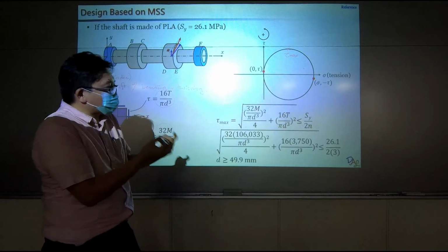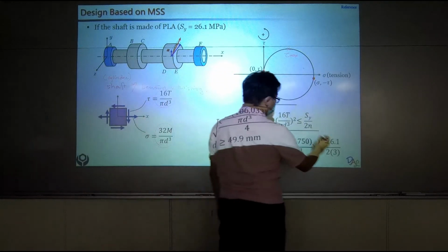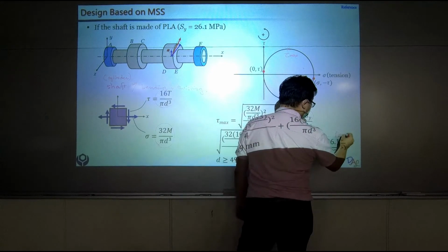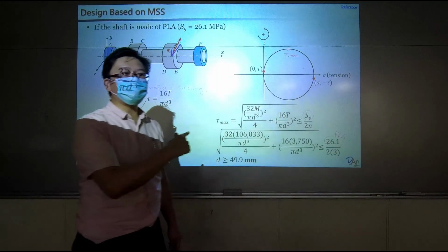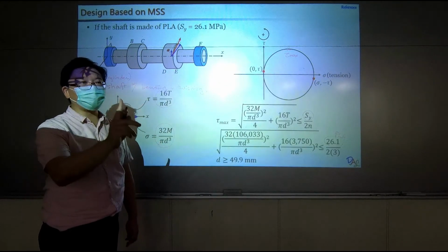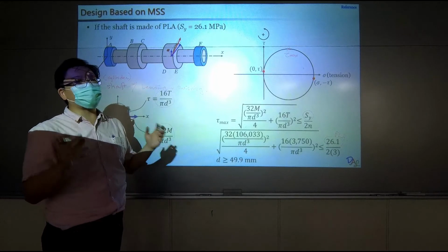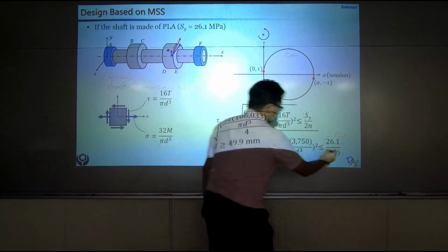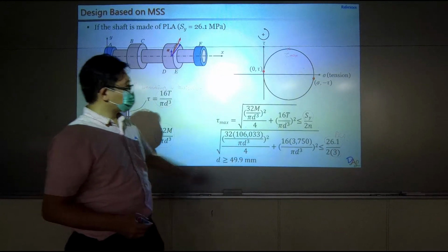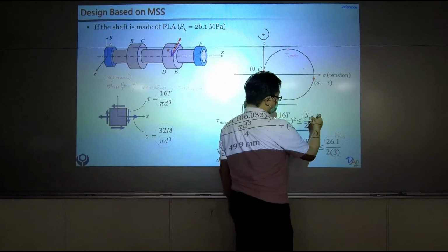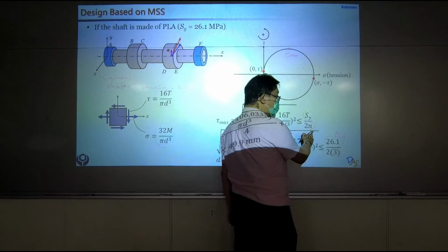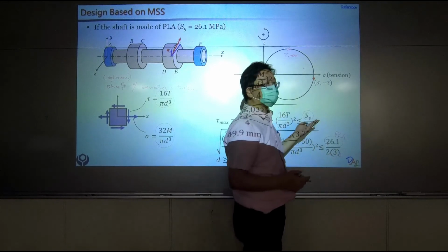Okay? But if we have something like this, what can we do? We can make very good use of it, because if we pick a material, this was PLA, right? And remember, in the earlier example, when we used PLA, the safety factor was close to 1. If I want this to be safer, if I choose 3, how can I make it safer? If I pick the decided material and also decide the safety level, I want the safety level to be 3.